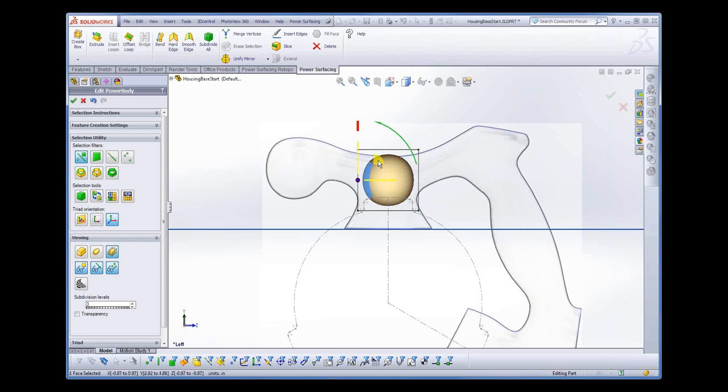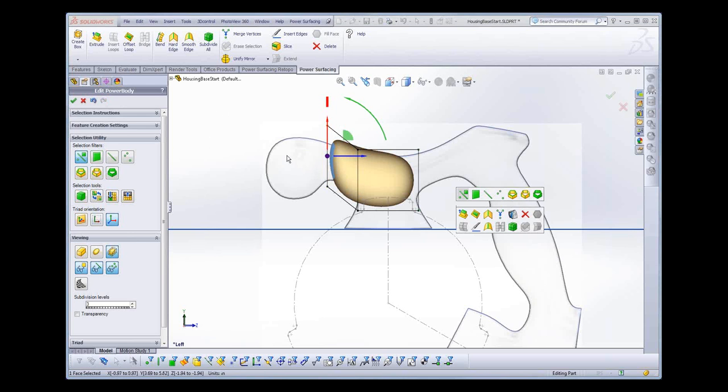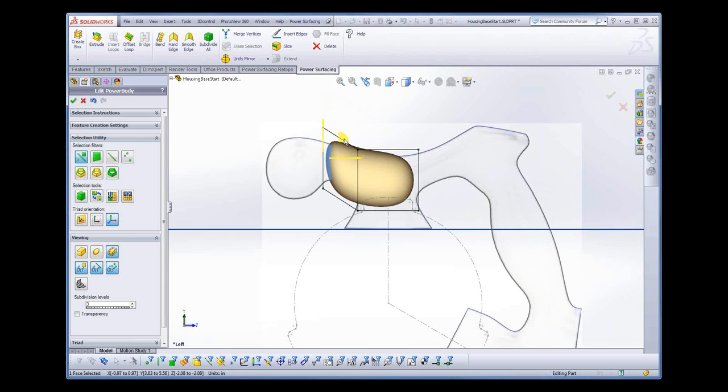So I'll hold my A key down and extrude. There was a question about the A key, asking what it does. Well, for us the A stands for add. It adds functionality. So it's a shortcut to do a lot of the regular tools. I just use the A key to pull this face out, which is actually the same thing as using an extrude, which we can either get from the ribbon or the right-click menu. It doesn't give us as many options, but it's a very quick way to block things in.